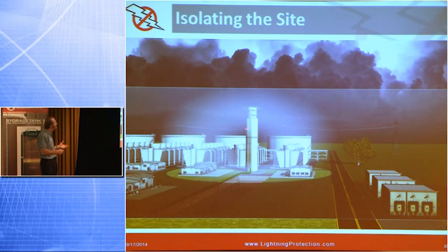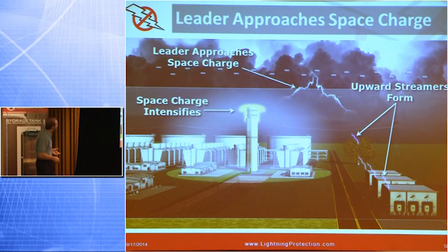What this really signifies is a very low electrostatic field in the area concerned in relationship to the surrounding environment. For example, we might have 5,000 volts per meter here and 25,000 volts out here. Why? Because we bled off that charge. We've neutralized it. We've allowed that flow of electrons slowly and continually during that 20-minute cycle. We're constantly bleeding that charge off, lowering the fields, keeping the fields low. Why is that important? Because now we have a lightning strike developed in the area. We have that lightning leader coming down from the cloud. Remember we showed you those big branch circuits? It's looking for an area to be collected.